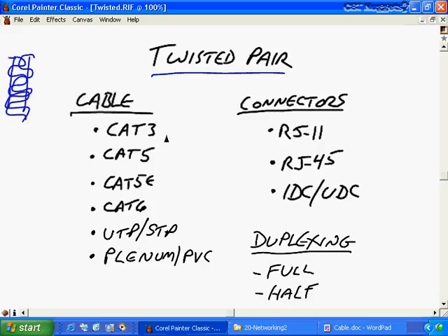There are several types of category cable. We call these category 3, category 5, and so forth, but we just shorten it to Cat 3, for example. With Cat 3, you have a minimum of 2 twists per foot, but that doesn't give you very good reliability in data transmission. They can go to 3 or 4 twists per foot. So we rarely, if ever, see Cat 3. You might see it for plain old telephone service installations, because most of these kinds of cables can be used for network data transmission or telephone service.